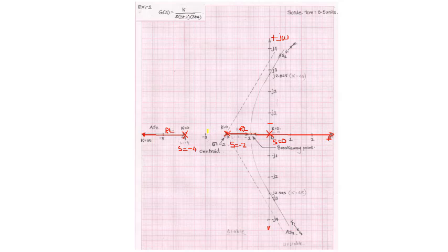Keep the protractor here like this, and measure 60 degrees from this side, that is in the anti-clockwise direction. Put a mark here. Draw a thin dotted line, which is going to go through the imaginary axis. It is called the asymptote angle 1, so it is called AS1.